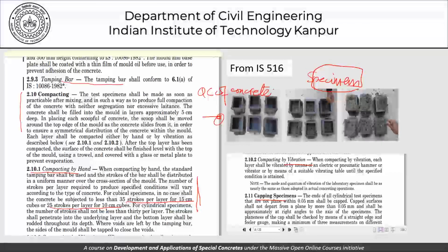Now, if somebody wants to know exactly what the strength of the concrete is in a beam that has been cast, the answer is that these cubes are only a reflection of that strength. They are not the true strength of that concrete, because the curing conditions are different, the placing conditions are different, the compaction conditions are different, and therefore in the strict sense a quality control engineer or a concrete engineer can never say that these cubes truly represent the strength of the concrete as developed.